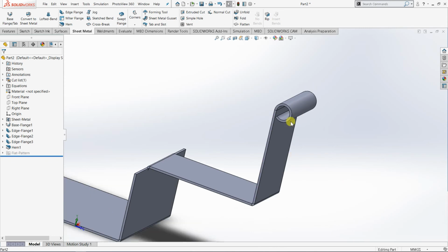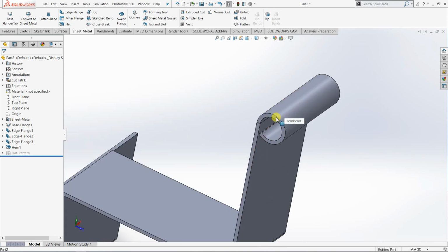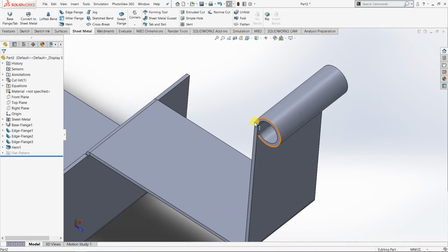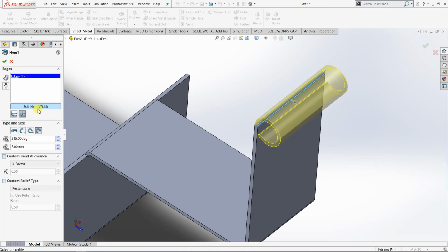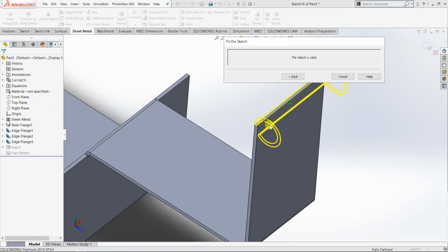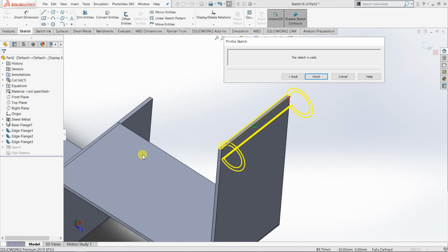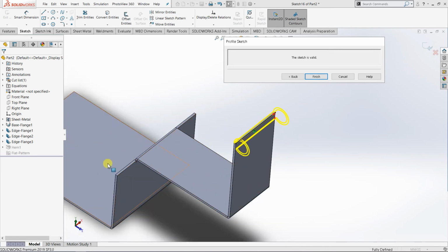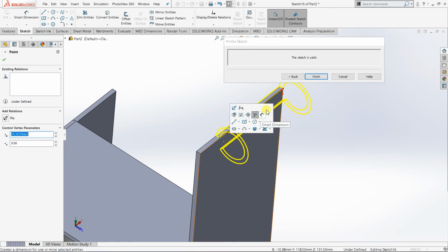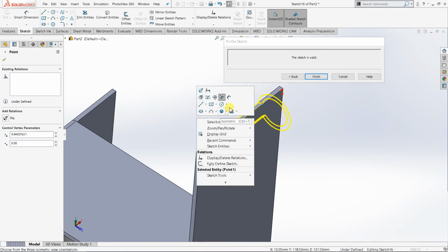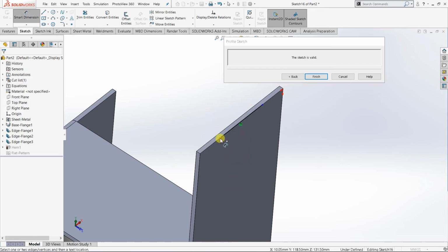Again, you can play around with the length of this hem or the width of this hem, from here to here, the length or the width. Go to hem here, right click, and then edit features, and you can edit hem width. Same with what we did for this one just now. You can even reduce by just adjusting both endpoints like that. You can indicate the dimensions from here to here.